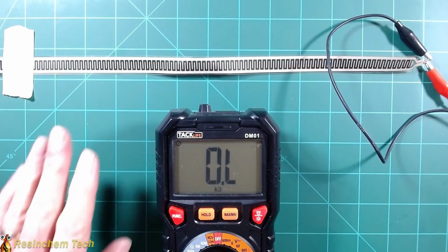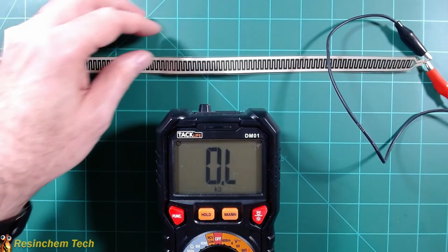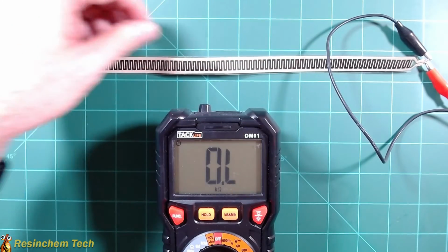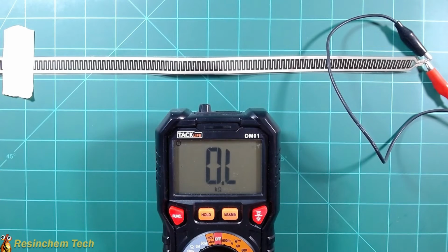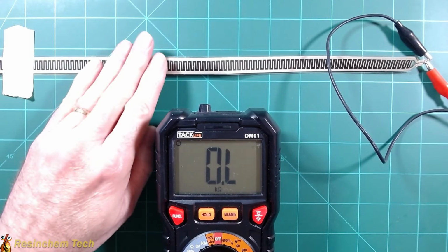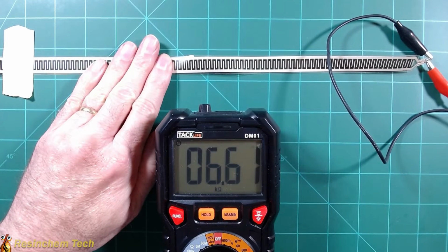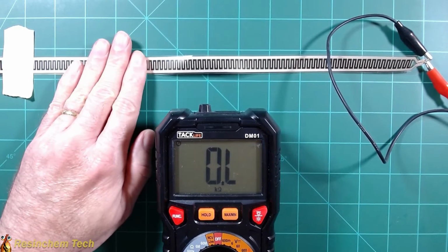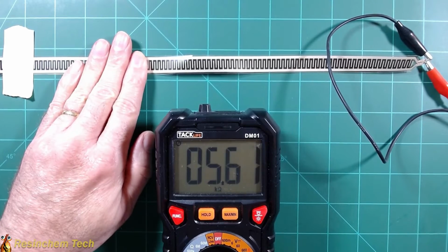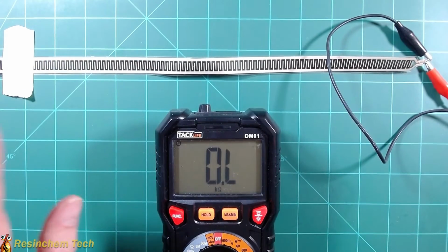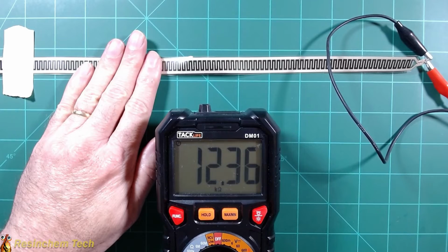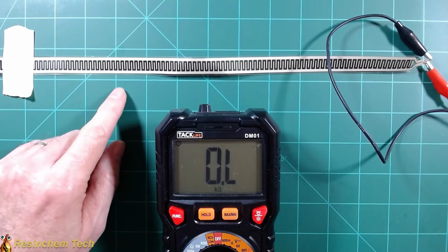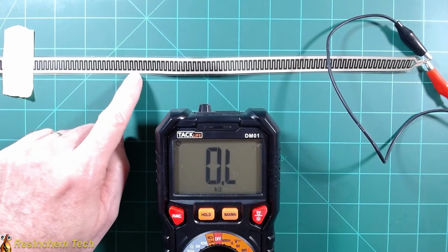So one of the first things I wanted to do was test this force-sensitive resistor because it was packaged and actually had some crimps in it, and that was a little bit concerning. So I just simply hooked it up to the multimeter here and set it to ohms for resistance. And I'm just going to apply a little pressure, and sure enough, I'm seeing a change in resistance with the pressure and how hard I press. So that's at least working. And now to get the maximum range for this, when it's actually in the bed, I need to determine what the resistance values are when I'm in bed versus out of bed, and that will help me determine the size of resistor I need to attach to this.